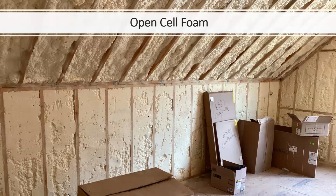Here's another shot of a really good foam install, but notice how different the vaults look compared to the wall. If the cavity depth of the vaults is 5.5 inches because it's framed with a 2x6, and the required R value is R19, then what depth of the open cell should I be seeing? If I do it with a probe, will it hit the black tape at 5.5, or will it hit something different?